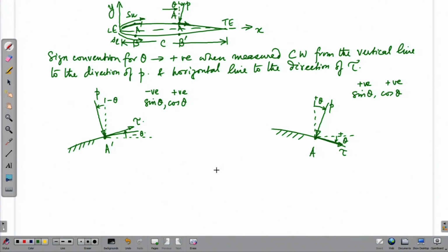Remember that the aerodynamic force acts over a certain length here. So, we will have to define a small element, we will call it ds. And if you were to define an area over which the forces were acting, then what you have to do is take the length of this element and multiply it by the span, which is essentially along the z direction.